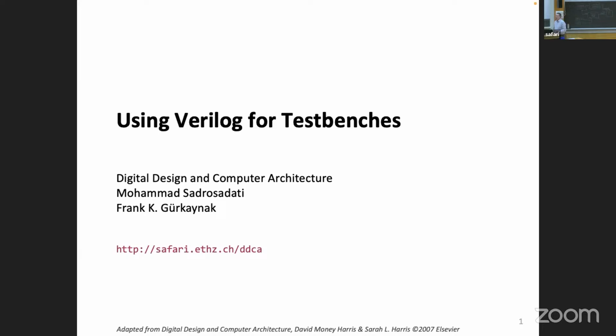If you make a circuit that operates on JPEG pictures, you can say this stimuli is a collection of pictures. This one is your Photoshop or GIMP or whatever photo processing program. And these are the resulting pictures, your golden outputs. Whereas here we have to translate it, push it to the device, get the outputs, convert it to pictures, and then we can check them both together. The interesting thing is, the upper part, this part, we can do offline.